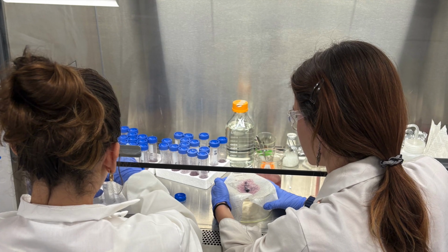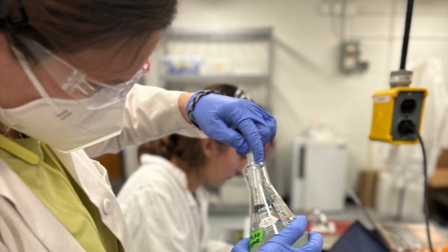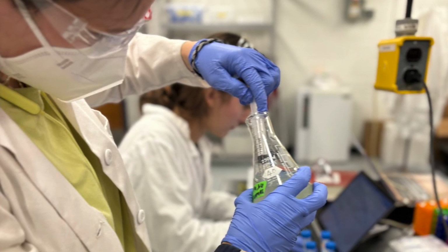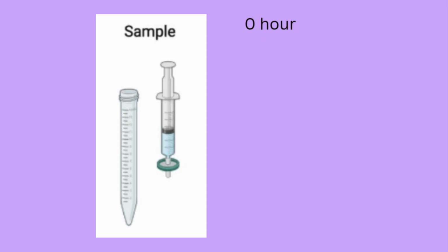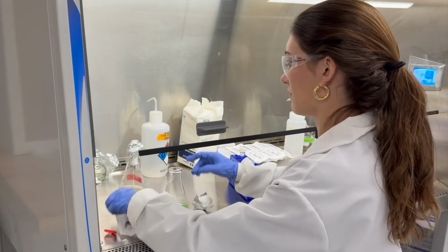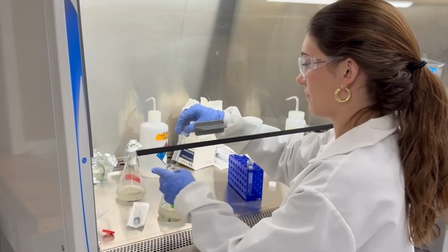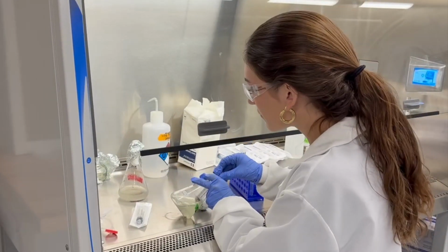We tested 2 pH values to identify the optimal pH for sorption, which helped determine the target pH of our effluent exiting the limestone pond. Aqueous samples were collected at 10 different time points to monitor and calculate the amount of metal adsorbed, assuming metals no longer in solution had adsorbed to the biomass. With the known values of the volume of solution, the fungal biomass, and the initial heavy metal concentrations, we were able to determine the best fit isotherms and biosorption capacities.